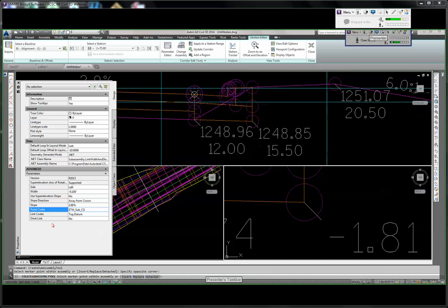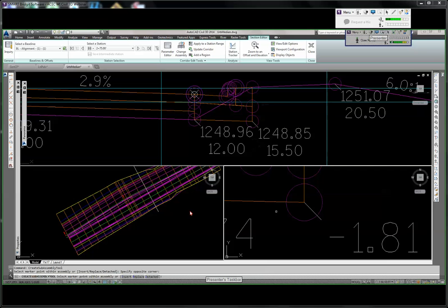I like to do it just to keep things clean. I'm going to turn the omit link to yes. It's one of those weird things where yes means I don't want it. So it's a backwards answer. I'm going to swing into my subassembly, left click on the point where I want it to attach, and you can see that it has created a point code